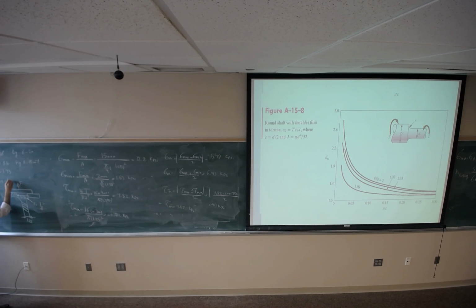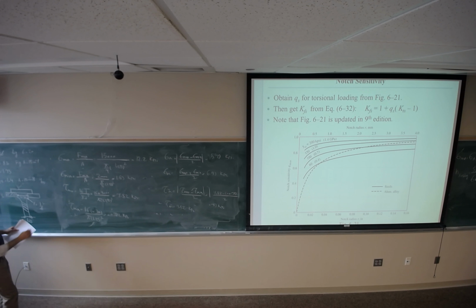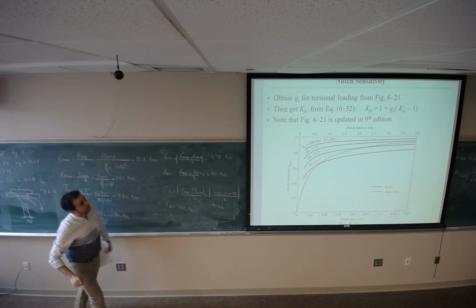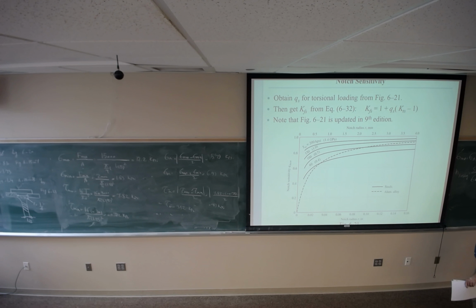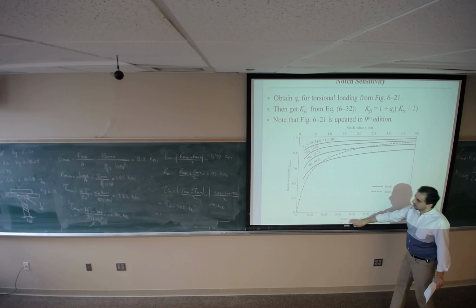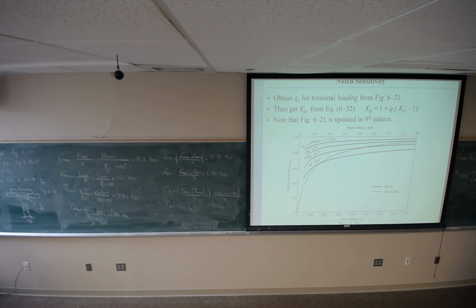Kts is going to be 1.4, coming from A15.8. And qs, figure 6.21. We are looking for the notch sensitivity, how much the material is sensitive to Kt.